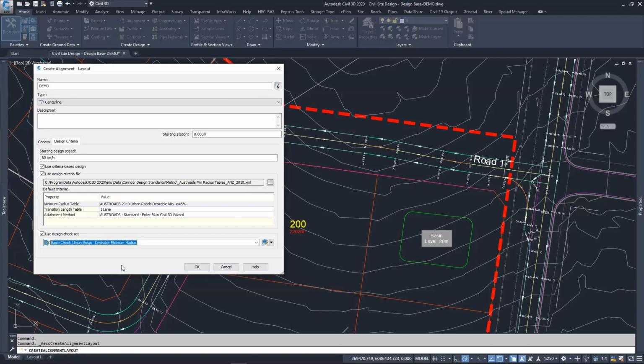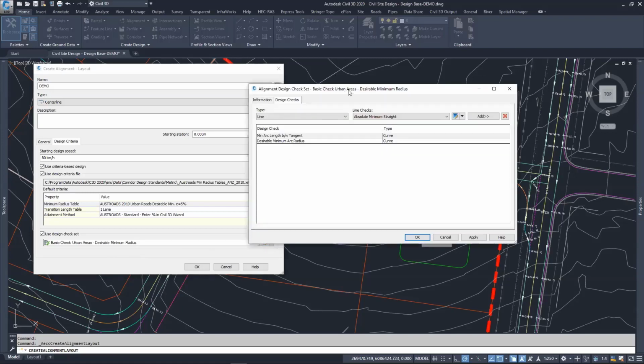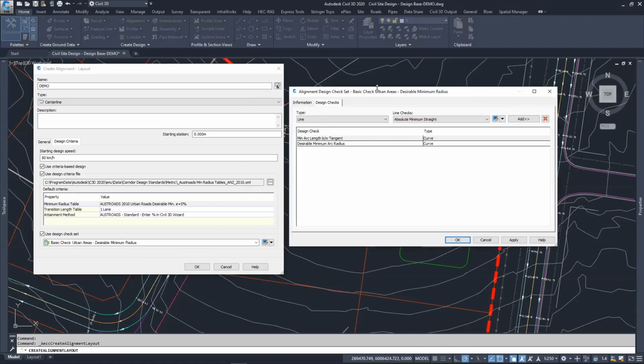if you can't achieve that with the site constraints, apply an absolute minimum, and then if you still can't achieve it, either make alterations to the site, and if you can't, then there'll have to be other compensations, like, for example, reducing the speed limit, because everyone follows speed limits, as we know. So you might want to go down that road if you can't achieve the minimum radius, for example. Now, in these, users can edit these. There's only one being applied for this one.